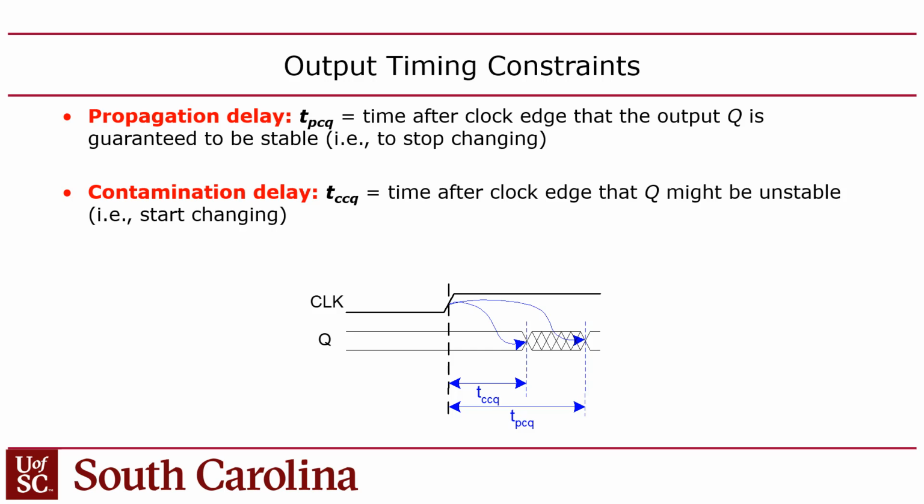So now the problem, though, is that generally in your CPU you'll have a memory element, usually a flip-flop register, and then you'll have some combinational logic between them, right? And these both have clocks. The idea is that within each clock period, you have one clock period to propagate through this combinational logic and be ready and stable for this register to clock in the result.